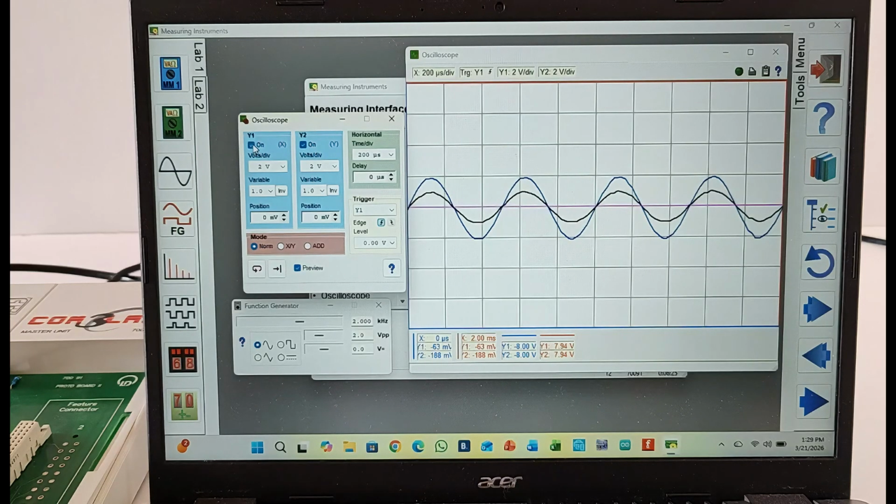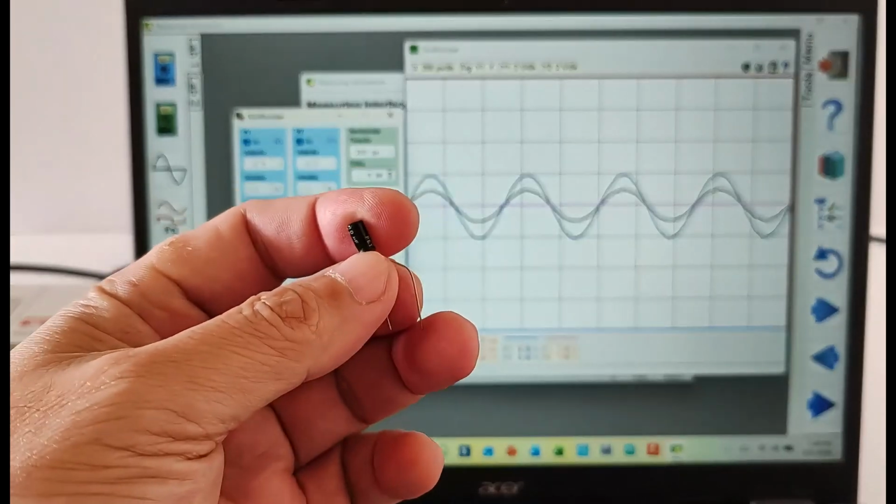This one is better. The output waveform now is running along the zero line of the oscilloscope. You can now see clearly the positive alternation of this waveform and the negative alternation, unlike the one earlier where it's slightly above, there's a DC offset if that happens. See here, right there. Here's the full waveform here. See here, right, guys? You now see the effect of that DC offset.